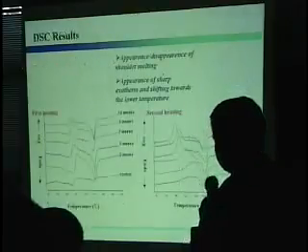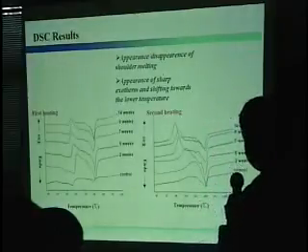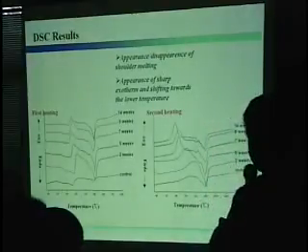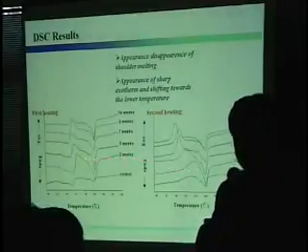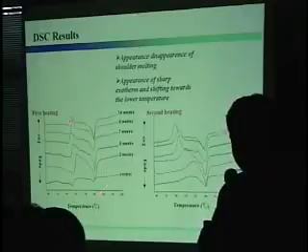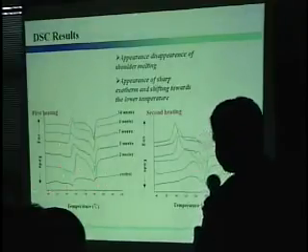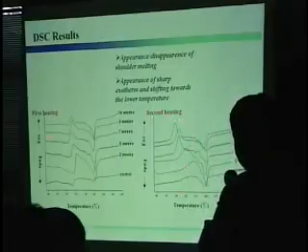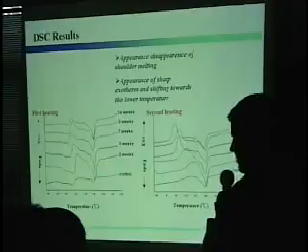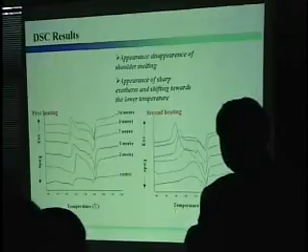Next slide, please. This is some evidence from the differential scanning calorimetry. Some thermograms you can see here at the different degradation times. This is the exothermic and endothermic position; the exotherms shifted downwards, to low temperature. Also, this is the second heating: first heating and rapid quench, and furthermore heating. Here also you can see the trend within the degradation time.